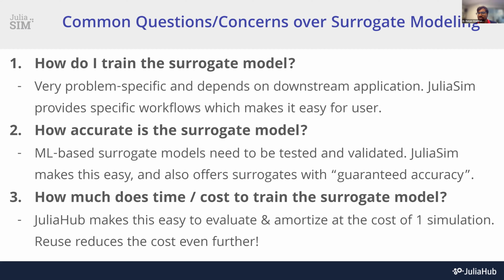Usually when you're building a surrogate model for a design task, which is what we're doing now, you're making a surrogate model of a simulator, and simulators are a source of ground truth, so you can get, in theory, unlimited training data from it given unlimited time. So it's quite straightforward to have enough data for that. And of course, if your simulator itself is not accurate, then perhaps it needs to be calibrated to be accurate and then generate the infinite training data. So yes, in most cases that overcomes the data problem.